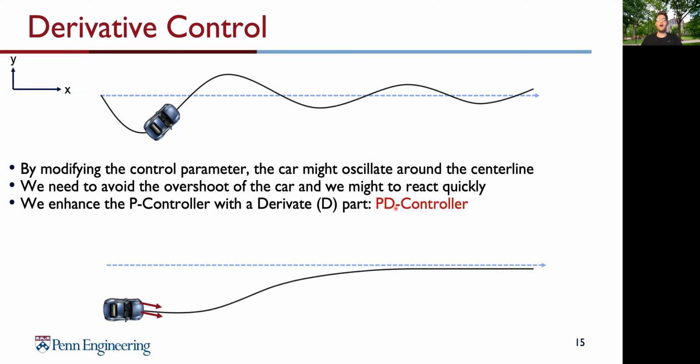You can imagine it like this. We will now approach the center line more slowly, but steadily, as we reduce the error. So when the car is turned enough to reduce our defined error, we integrate the new term, so our car figures out that it can steer to the other side again, because it's approaching the error itself.